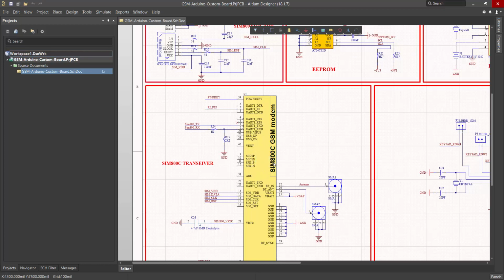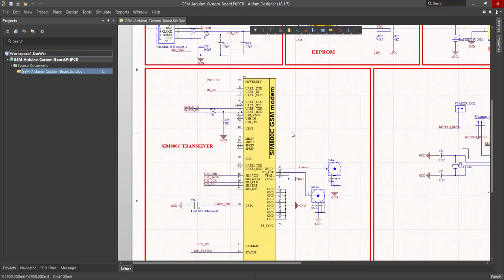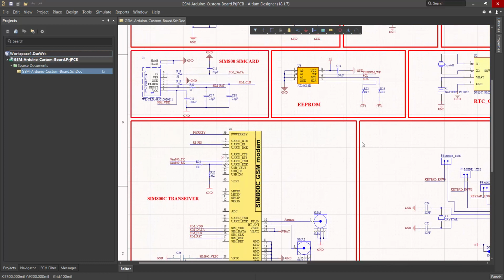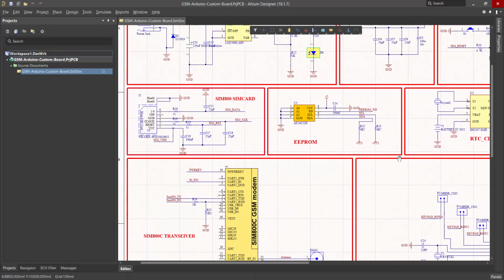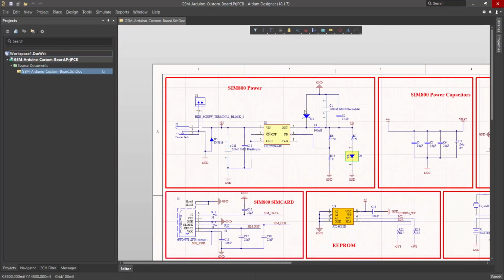So there isn't any standard fixed voltage regulator for this range in the market. There are 5 volt, 3.3 volt, 1.8 volt and 1.2 volt regulators, but they are not suitable for this range. Therefore, we should use an adjustable version of linear regulators, or like this, DC to DC converters.